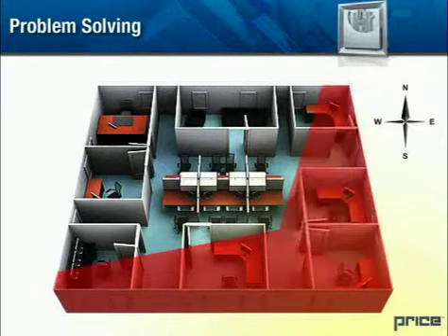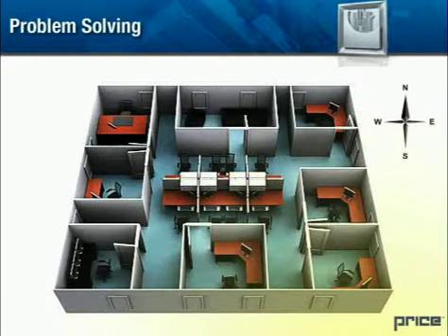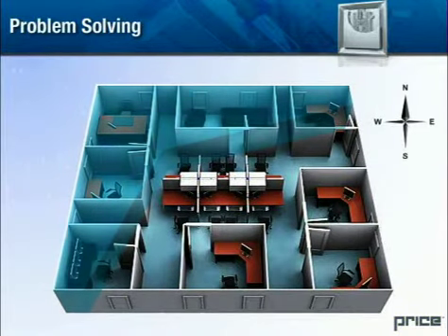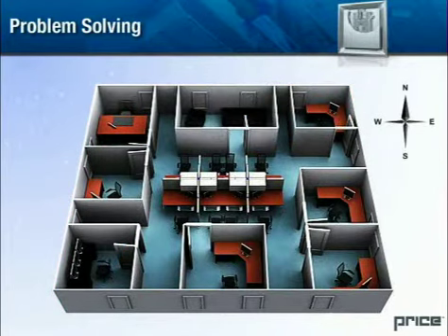The south and east side of the building experience a greater solar load than any other portions of the building and will require a larger cooling period. The north and west walls will require a larger heating period as the solar load for these faces is smaller.